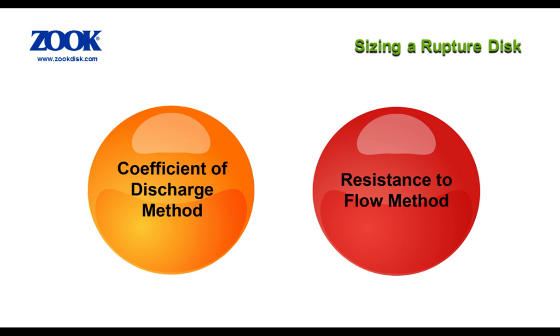Caution should be taken when selecting rupture disk designs based solely on a low KR, as this can lead to a smaller diameter relief line and limited options to correct the situation if changes in the disk design are required in the future. Vendors can offer useful advice and sizing assistance, but ultimately the responsibility for sizing lies with the end user. The takeaway here is right sizing, and to provide right sizing, a collaboration between the user, process engineer, and the disk manufacturer is essential no matter what method is selected.